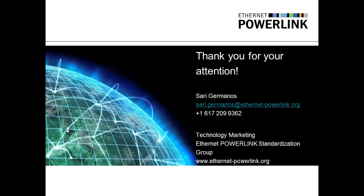And lastly, POWERLINK is actually very good on video. So if you're trying to do video or imaging of any kind, that's very slow on EtherCAT, whereas on POWERLINK I've seen examples where there were two live video feeds, compressed high definition video, and you have a system running at a 400 microsecond cycle time, and everything runs flawlessly, and the video was jitter free.